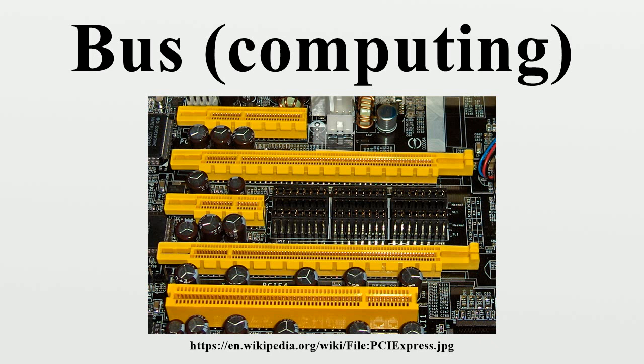Often, a serial bus can be operated at higher overall data rates than a parallel bus, despite having fewer electrical connections, because a serial bus inherently has no timing skew or crosstalk. USB, FireWire, and serial ATA are examples of this. Multi-drop connections do not work well for fast serial buses, so most modern serial buses use daisy chain or hub designs. Network connections such as Ethernet are not generally regarded as buses, although the difference is largely conceptual rather than practical.